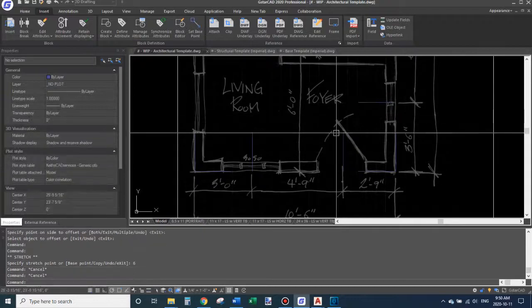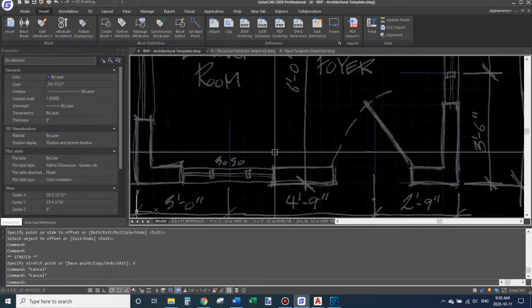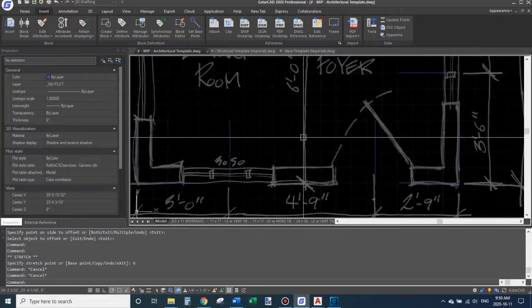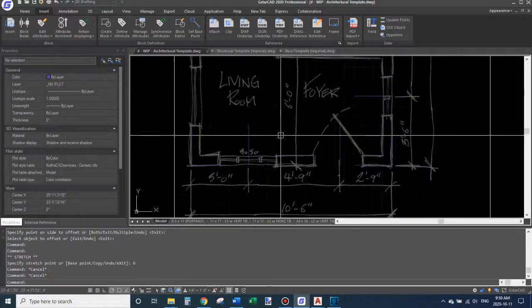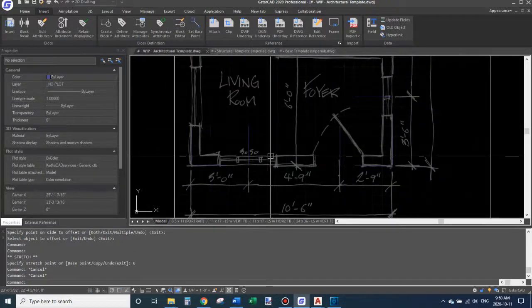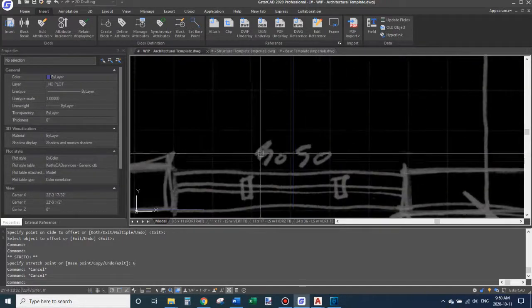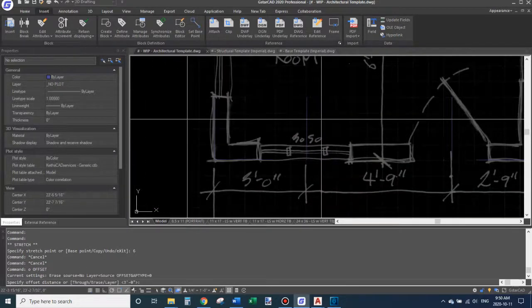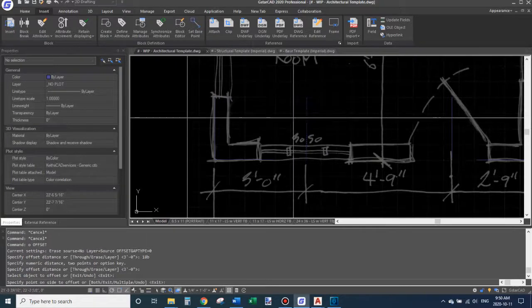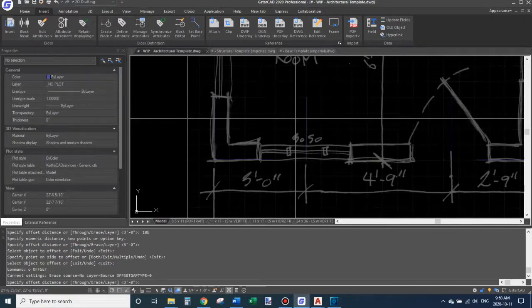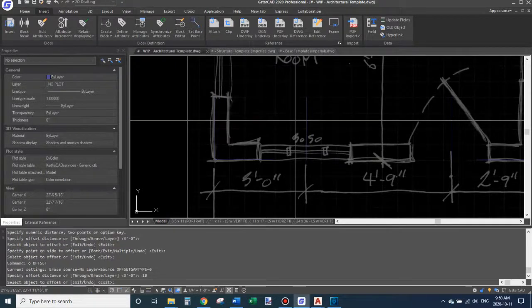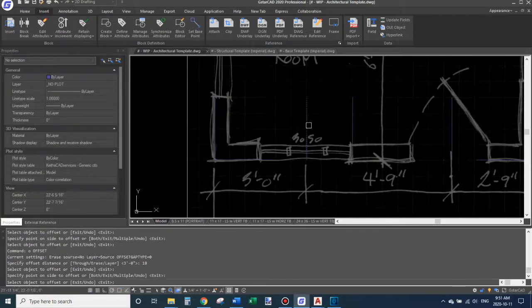So when I drew this, what I did was made 2 grid squares equal 1 foot. So oftentimes you're wondering how wide do I make the windows? Depending on their standards, like a window like this might actually mean 3'0" wide by 5'0" high. So this I just offset at 18. Oops. There we go.